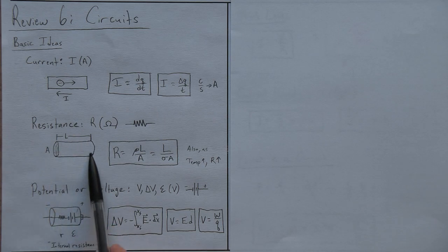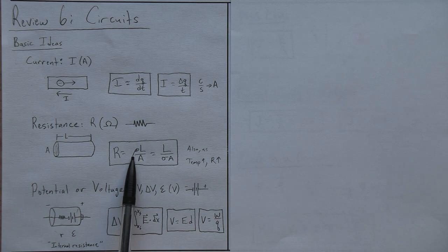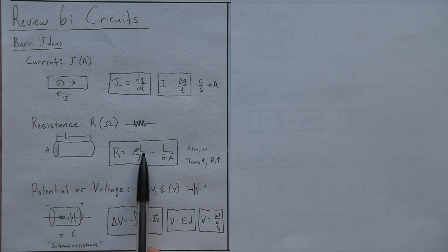This symbol, resistivity, is there because different metals, copper, gold, aluminum, if you make them all the same size and shape, will all have different resistances. So this is the resistivity that depends on the particular conductor that you're dealing with. You look that up, or maybe you have to solve for it within this problem if everything else is given. So more resistivity, more resistance; more length, more resistance; more area, thicker wire, less resistance.